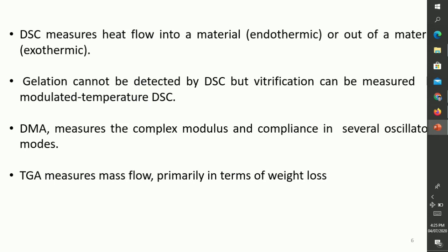These are the measurements that can be done successfully using a differential scanning calorimetric instrument. The most important is the detection of phase transition temperature or glass transition.